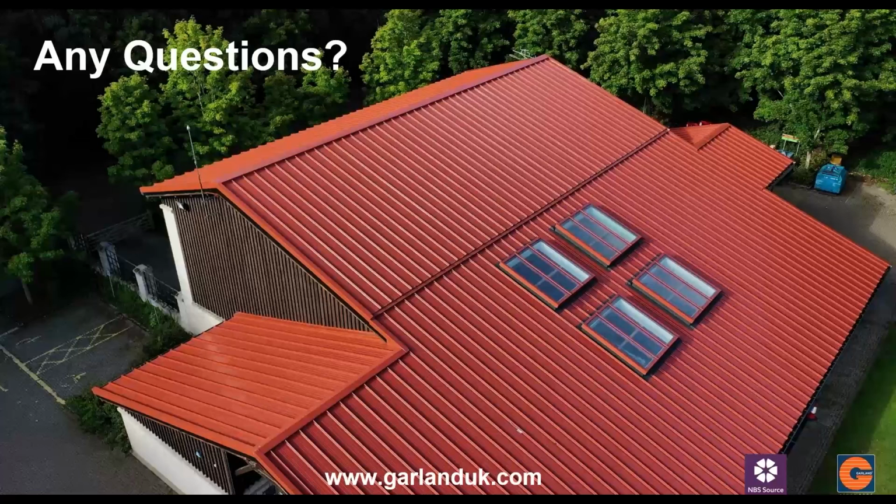Thank you. The next one is from Alex. He asks, I work with NHS trusts who often require flame-free roofing products on their projects. Are these actually reliable in the long term when compared with metal or torch applied bitumen membranes you talked about? Hi there, Alex, and thank you for your question. Safety torch is a very prominent topic that we're coming across at the moment, and you point out a very good point. So torch-on systems, depending on the quality of the membrane, will typically last longer than the self-adhesive because you're torching and actually bonding that membrane to your substrate.